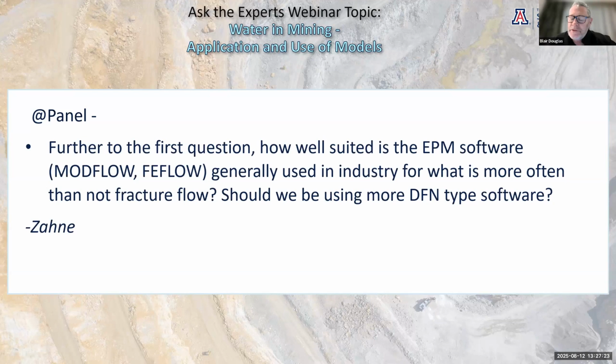I might just add that there is a use for them though, isn't there? Where the geotechnical analysis shows there's a strong correlation between a failure mechanism which is driven by a specific fault, which is detailed and mapped, and it may have specific properties relating to clay content and water content, whether it's saturated or unsaturated.